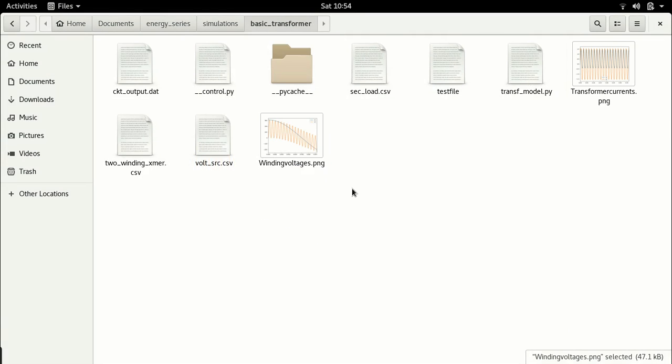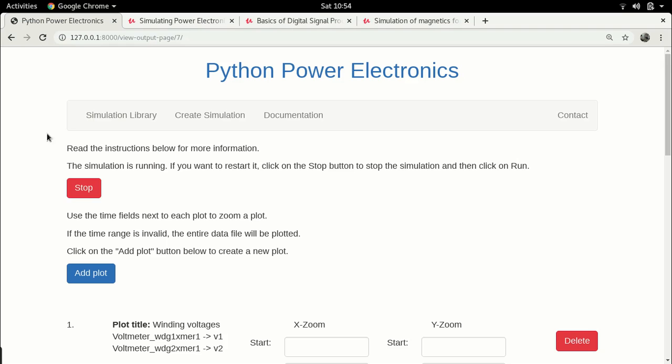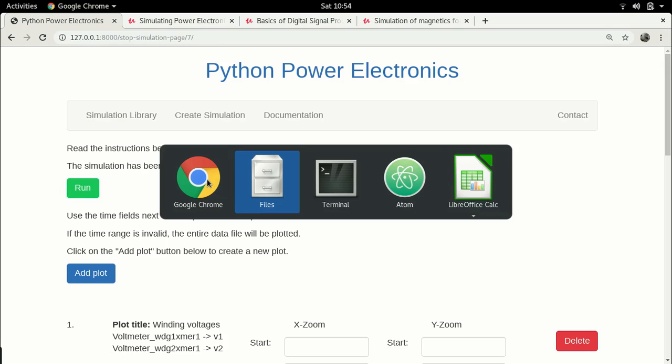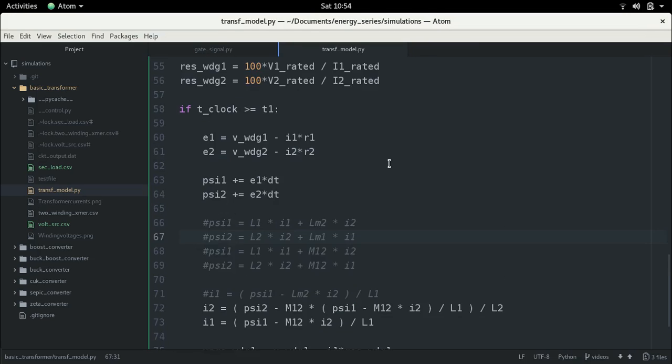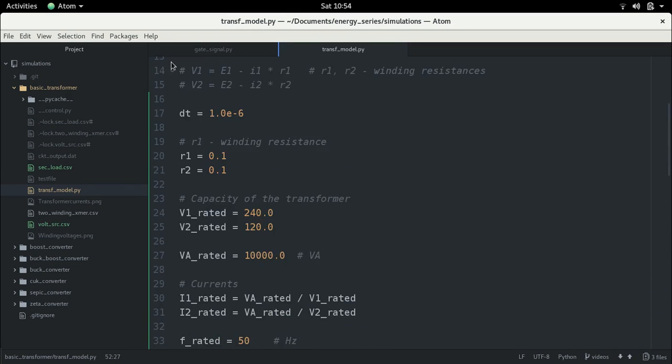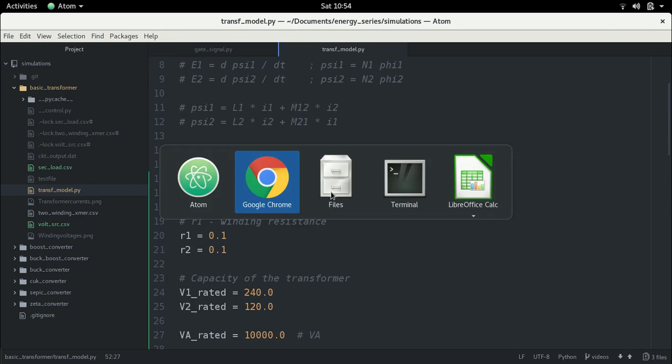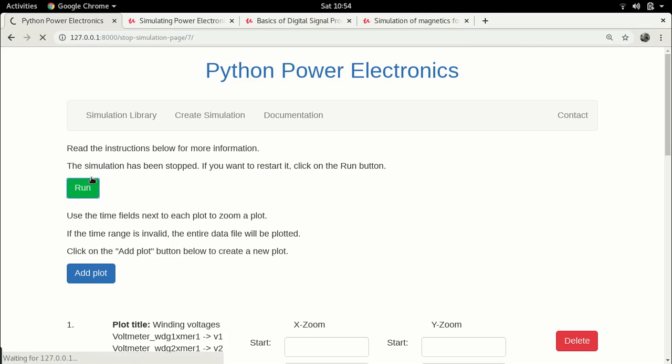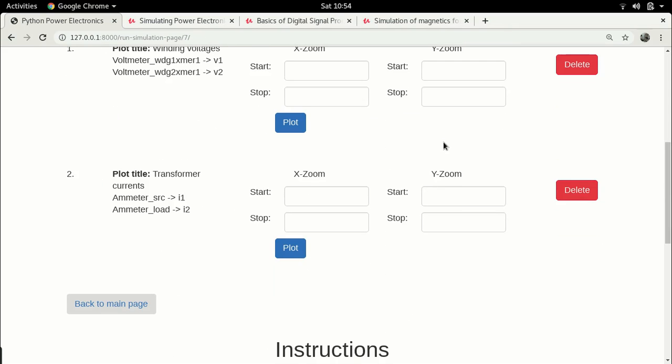The next thing we need to do is deal with this large instability problem that we are having. I would just go increase this again. Eventually we would have to decrease this time step, but I would rather wait for that because that will only slow down the simulation.